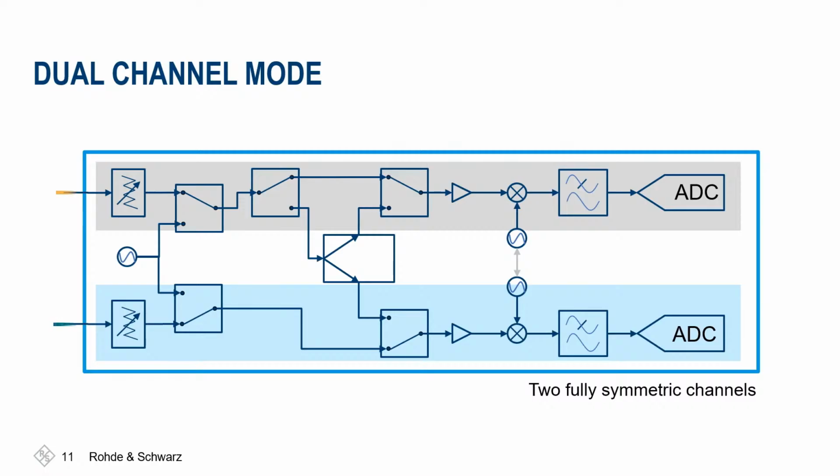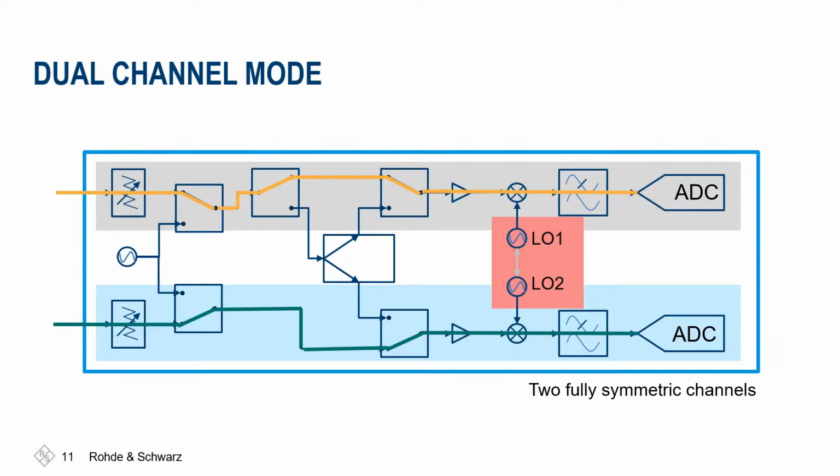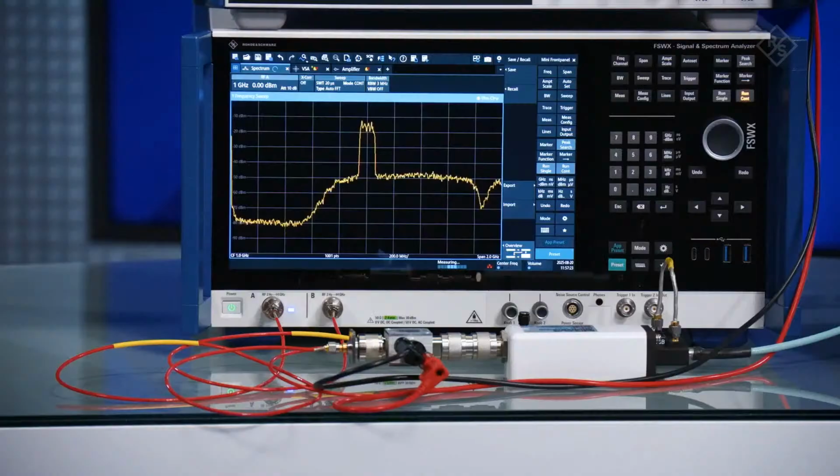We can again see the two signals traveling to the two signal paths that are exactly identical to the previous high power PA demo. However, what I want to highlight here is that the two signal paths have two different and independent LOs. So I can tune the orange signal path to frequency number 1, which is the output frequency, for example, of my device under test. And signal path number 2 can be tuned to a different frequency, representing the input frequency of the device under test.